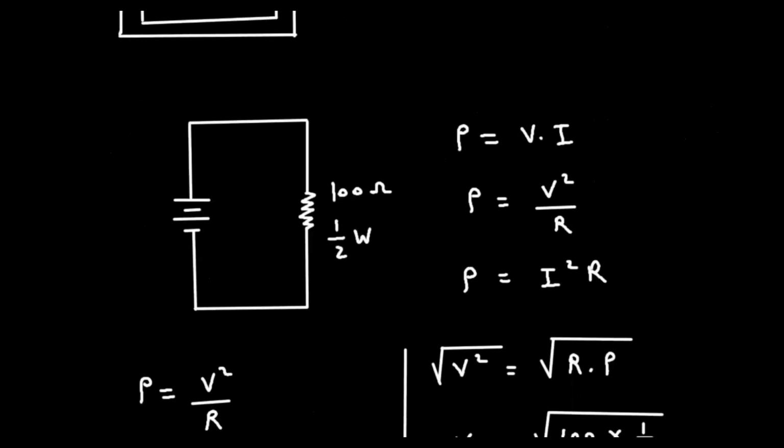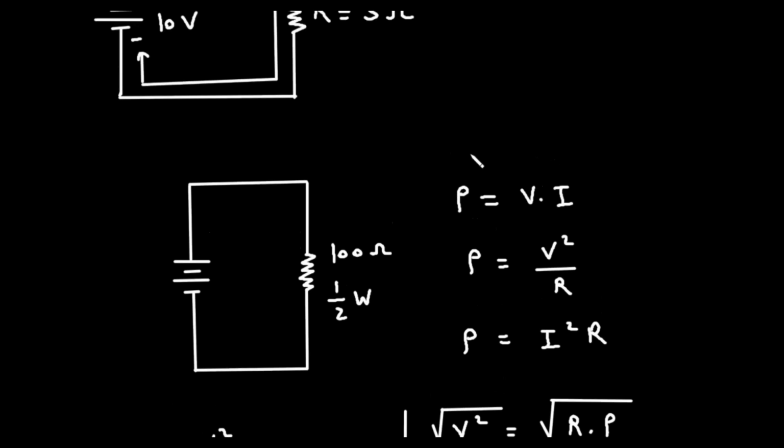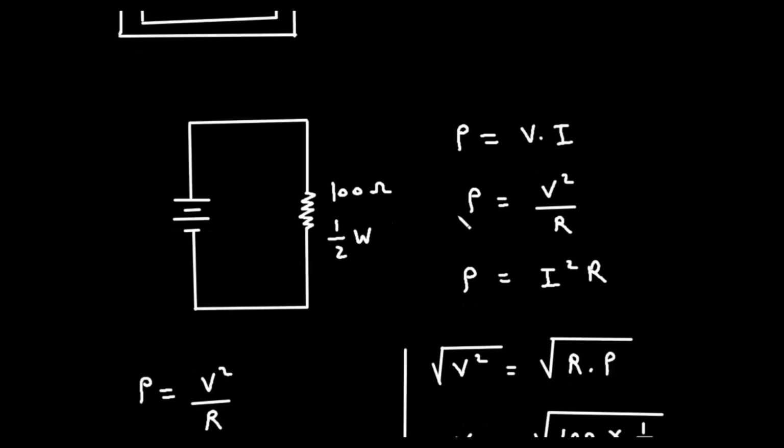Now next is power rating. So here we will understand this with an example. Every resistor can only handle a certain amount of heat, measured in watts. So here we can see this is the power rating. Half watt is the power rating of this resistor. Commonly these ratings are 1/4, 1/2 or 1 watt, etc. If the current is too high, the resistor may burn out. If the current is more than this power rating, then this resistor will burn out.